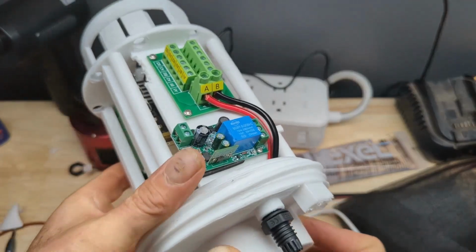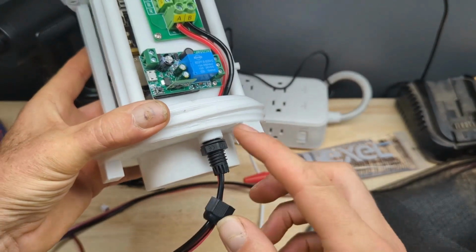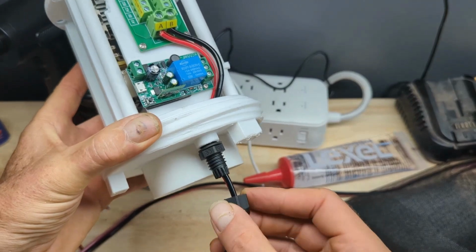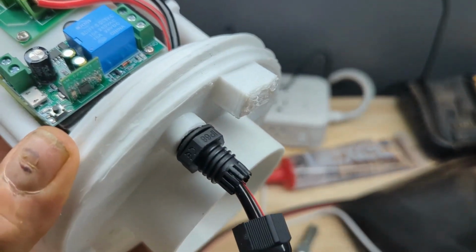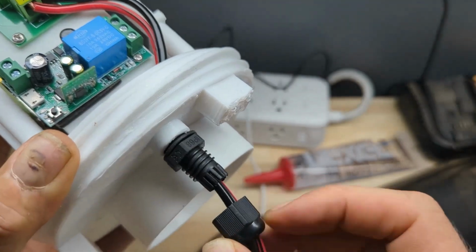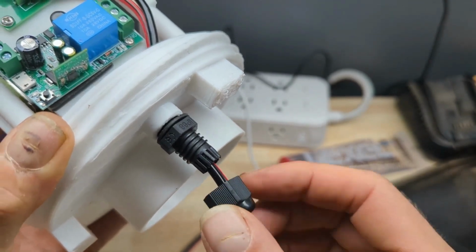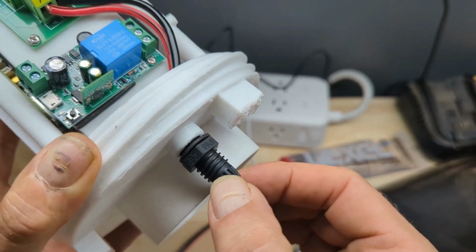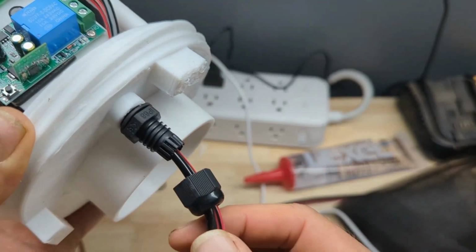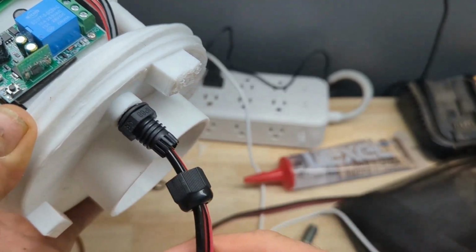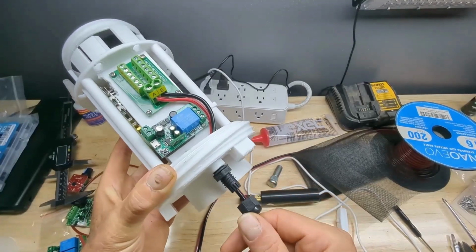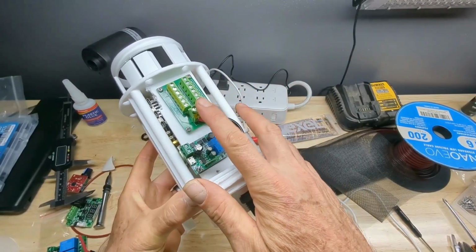And then one other thing I want to point out is I failed to do this. This cable gland, once you get the power in there, you do want to make sure that you secure it. See these little fingers on here? As you put this nut on here and twist it down, it's tapered inside, and it will start squeezing these fingers down really tight so that this wire would have a very, very difficult time pulling out, because you don't want to snag this wire and have it get yanked out of your power block.